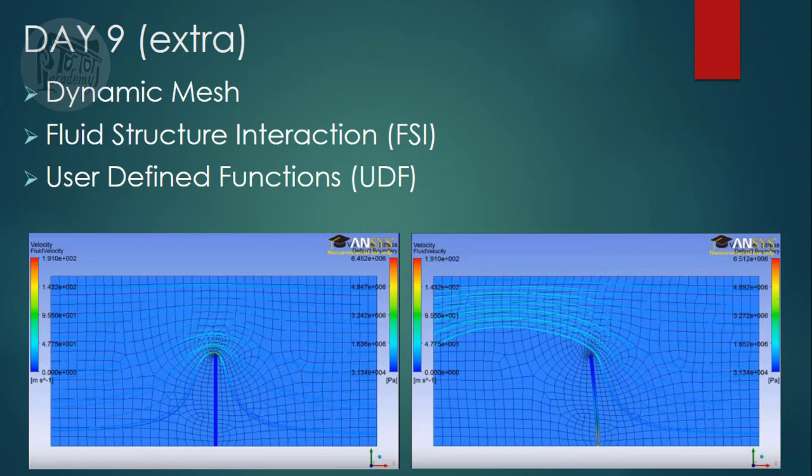This is the fluid structure interaction, and it is very important for aerospace applications, because starting from the design of fans and propellers, it is very important in the verification of the design of pre-twist. If we have a pre-twist in the wing, say we have a wing for a certain airplane, due to the moment coefficient or the moment on the wing, we sometimes do a pre-twist, twist the wing or the propeller in the direction that is opposite to the direction that it will twist to under flow.